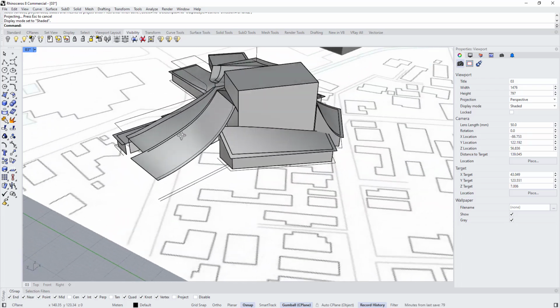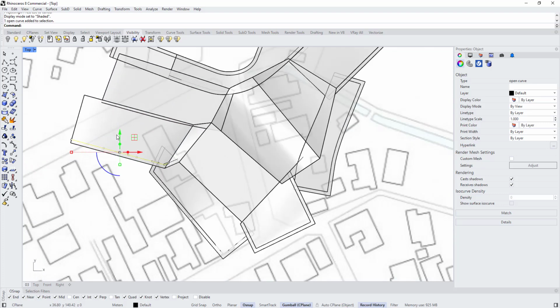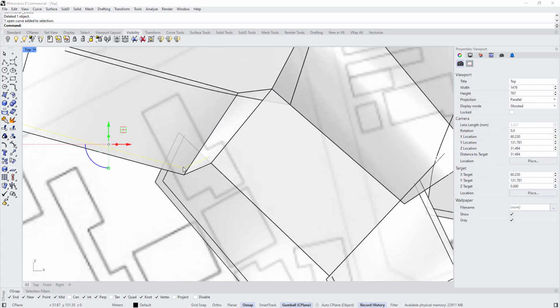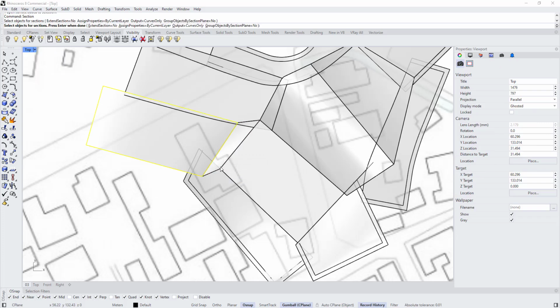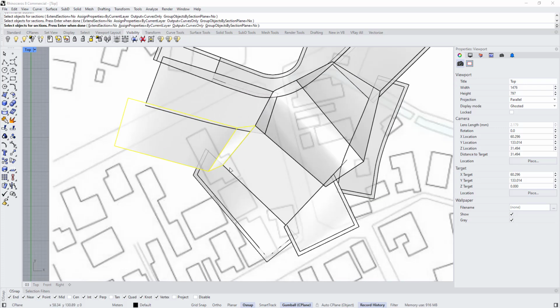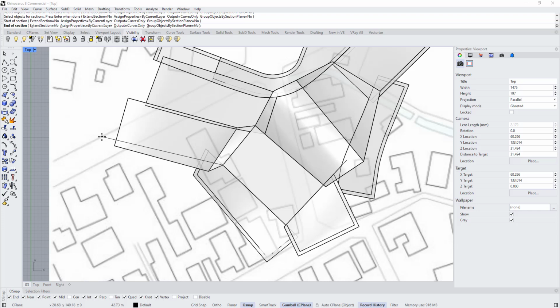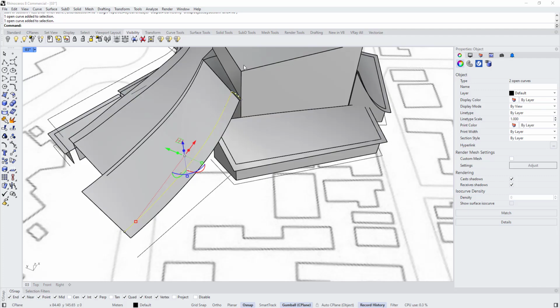Okay, it looks a little bit weird by the way. This one. We can create the wall by another method. Select this surface maybe, and this one too. Then choose section and maybe draw some kind of section here to get these lines.